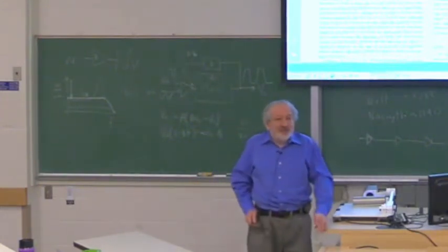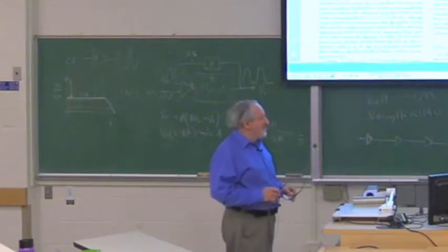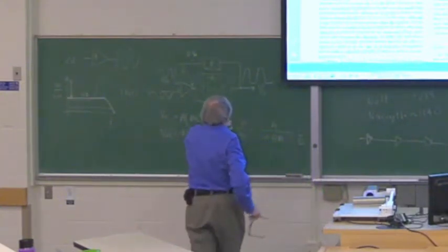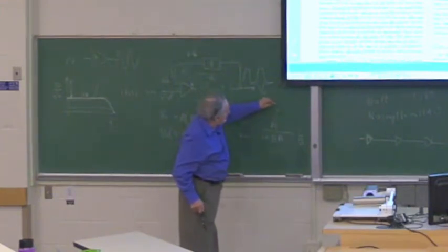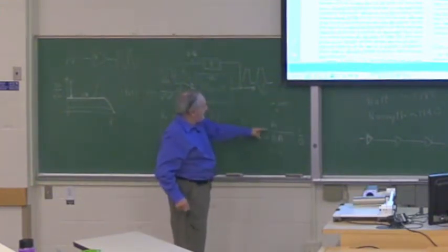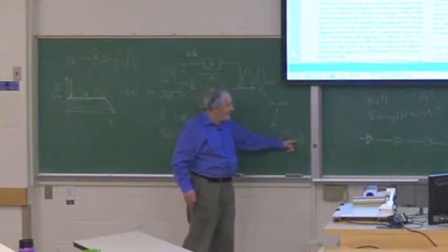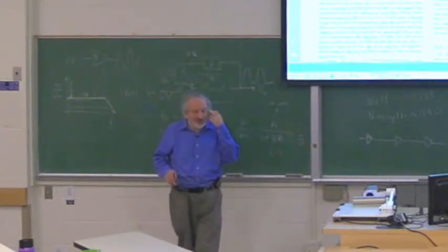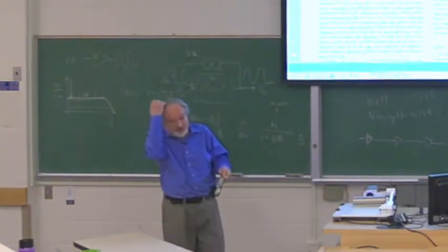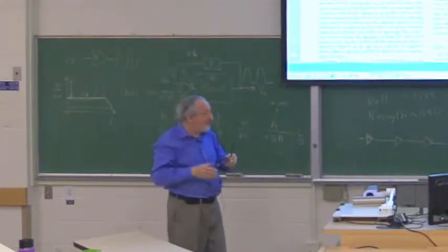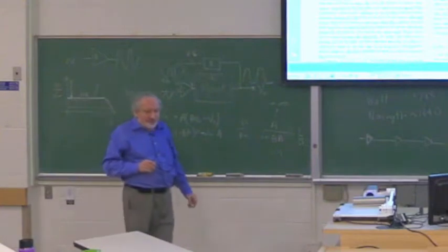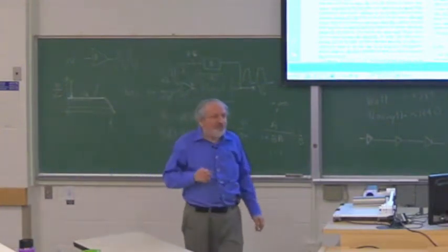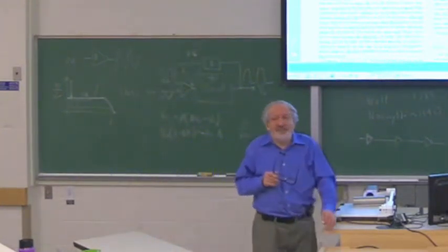Good. So Black understood that and said, if you do that and throw away most of the gain, in other words, if you make A go to infinity, very high, not only will we get a constant output 1/B, but the distortion will go down a lot. Roughly by how much excess gain you have in the system. But Black understood something else, which is very critical.